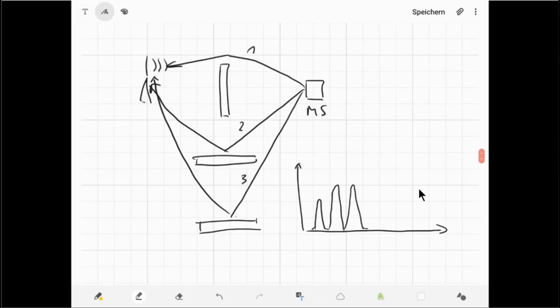And the receiver now has the difficult task to make one symbol out of this received signal. The receiver might not know what actually was sent, but with the help of a defined training sequence, the mobile station in this case would send this training sequence, and it would lead to such a characteristic reception like shown here in this timing diagram.